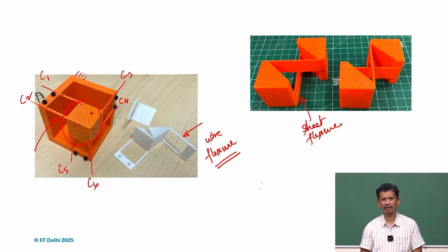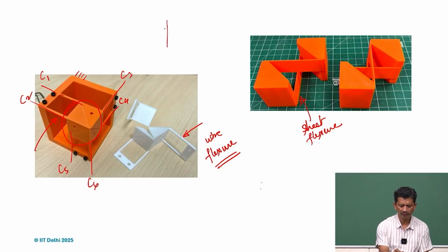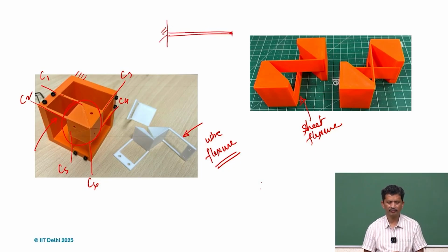And yes, we use a pair and we can make cross flexures, which will act as a hinge, or if they are in parallel, then we can design parallel guiding systems. In the 2D case, what we realize is that it is just a very slender element.